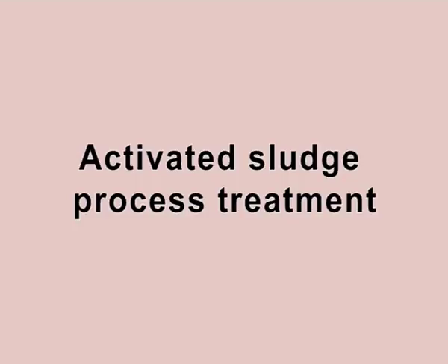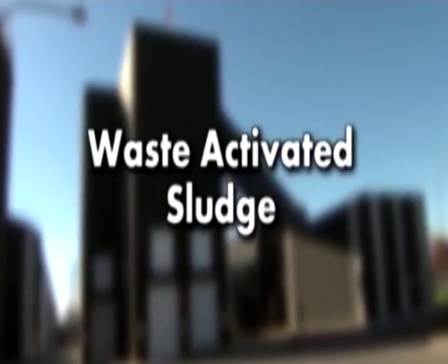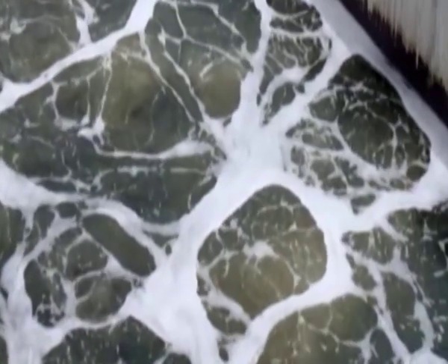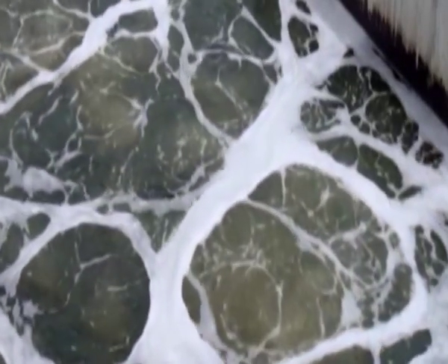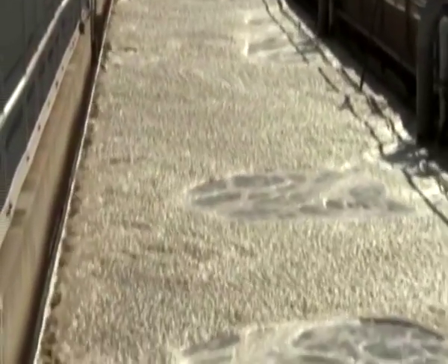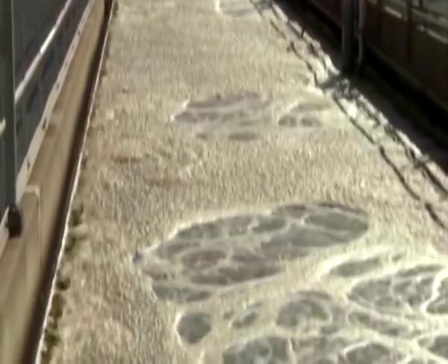In an activated sludge treatment system, an acclimatized, mixed biological growth of microorganisms is brought into contact with organic material in the wastewater in the presence of excess dissolved oxygen and nutrients such as nitrogen and phosphorus. The microorganisms convert the soluble organic compounds to carbon dioxide and cellular material, that is new biomass.